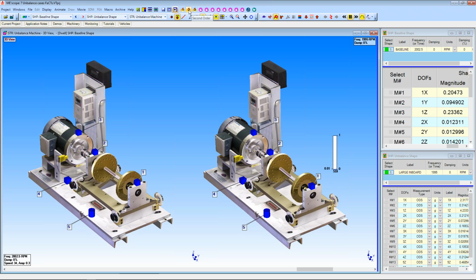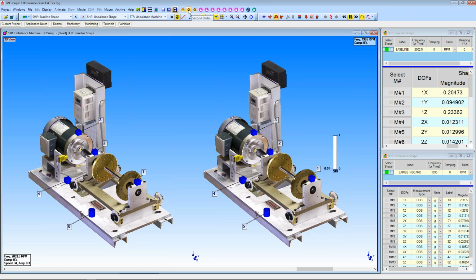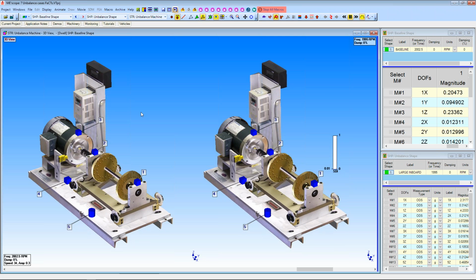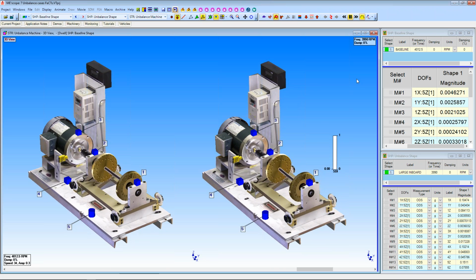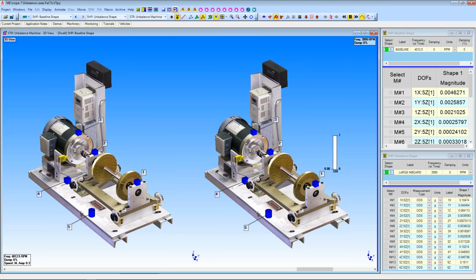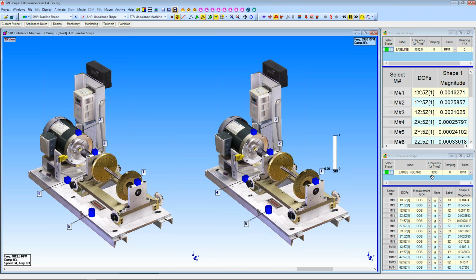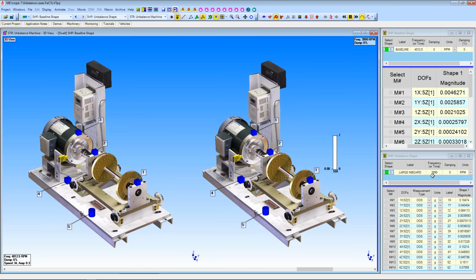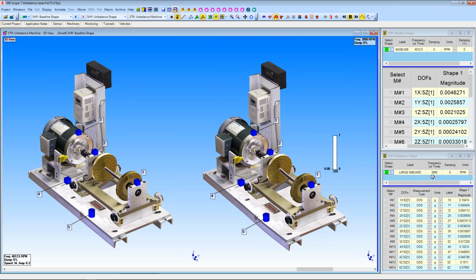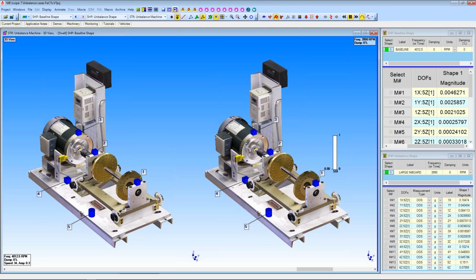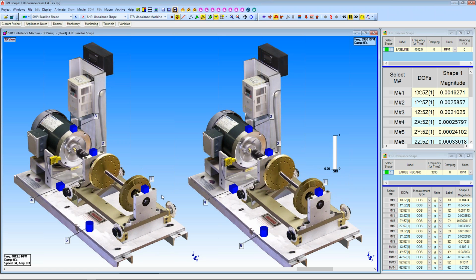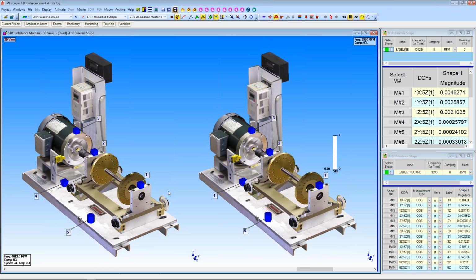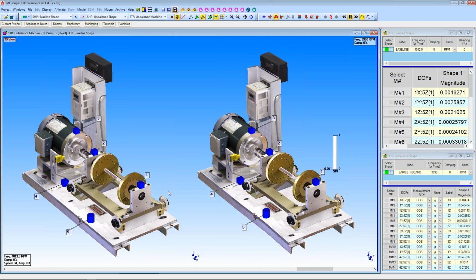Let's go and look at the second order. So this is taking the 4,000 RPM data and doing the same thing with it. So you can see up here the baseline is now 4,000. The large inboard is at essentially 4,000, 3990, and you can see that the second order ODSs are indicating the large unbalance also.